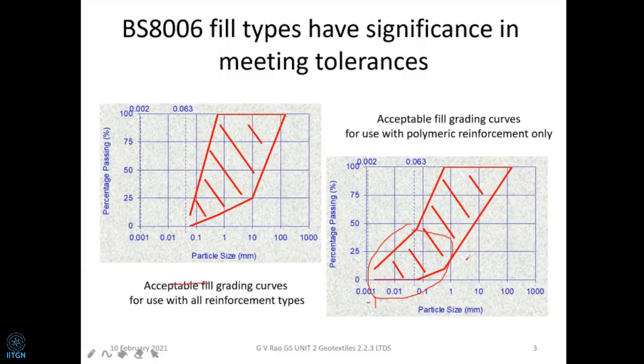And in course of time, if by any chance water gets into the structure by some other means, naturally it will drain away very quickly. But in order to drain water away from this wall, sometimes we have to provide geotextile. Sometimes we provide some pipes and things like this. So all the details I have shown you just quickly in the code, and we also have our own methods in India. The point is that we take care of this in order to see that the water table is not going to go up to the top. Somehow or other, we are trying to see that the structures are considered free of water.